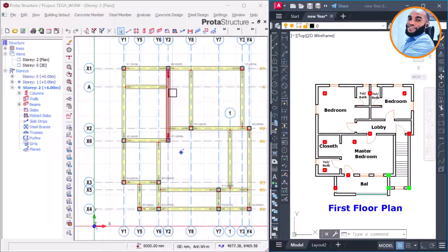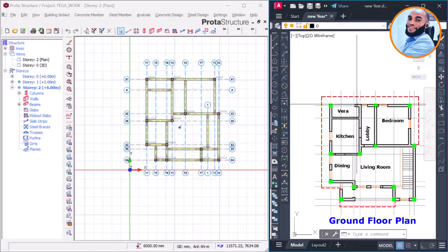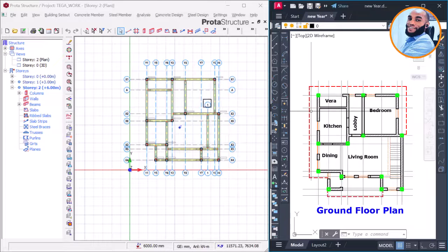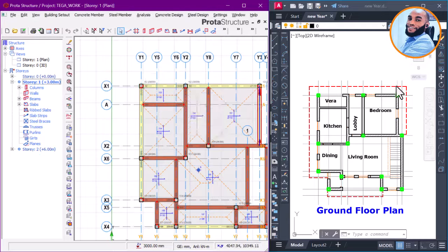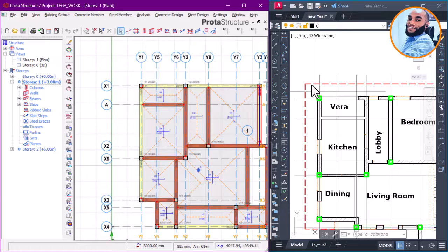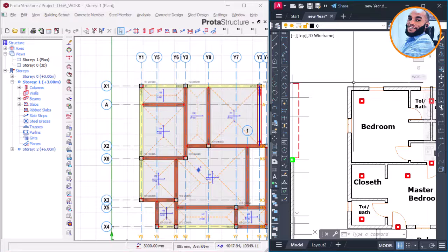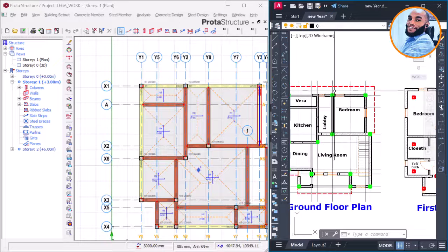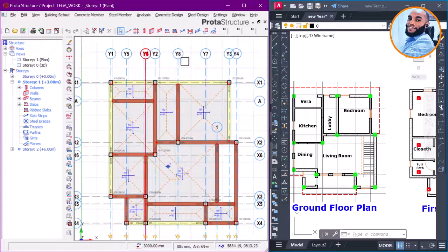Before I make my changes, I will first have to model this cantilever slab on the ground floor, which is story 1 here. So I have to make my story 1 active. When you are modeling your cantilever slab on the ground floor, you also need to consider cantilever beams, which are going to carry the columns. But first I'll teach you how to model the cantilever slab. Although I have done that a lot, if you are new here on Ekidel, then I will teach you that.